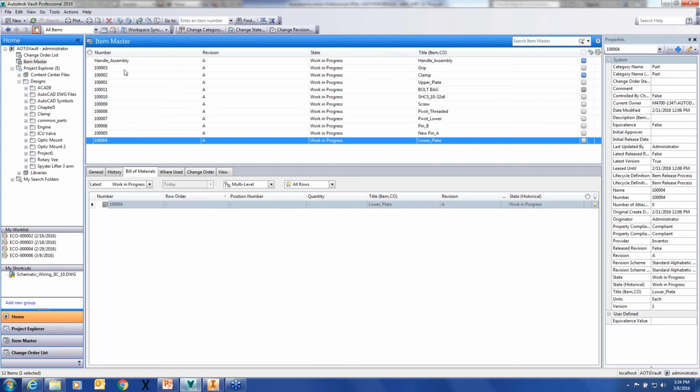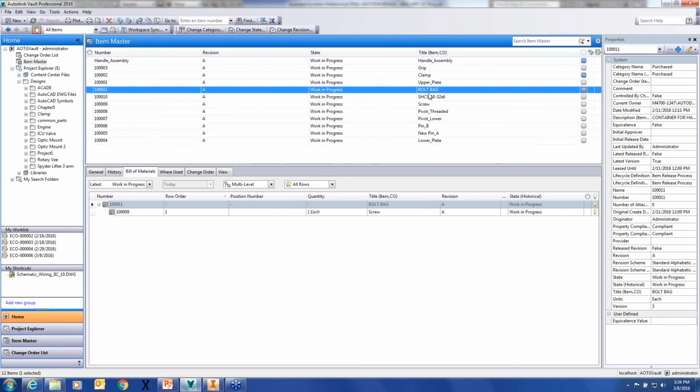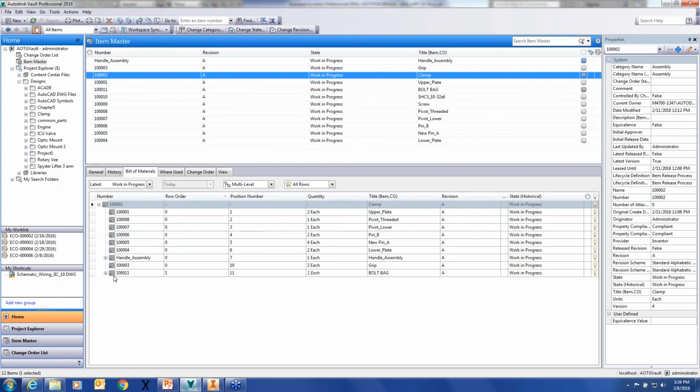So items, obviously, you want them to be connected if there is a CAD file, which is typically the case, but there might also be other files in here, like we created just a bag of bolts here that maybe goes with your assembly, and that one wouldn't have a CAD tool. Maybe they just throw stuff in there for spares or something like that. So you can add just regular items not connected to a CAD file. You can add those into your bill of materials here, and then eventually export those out to a CSV file where it can be imported into your ERP